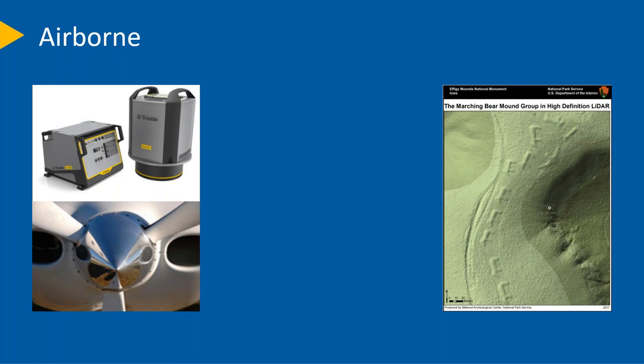Benefits you'll see from airborne LiDAR is you can capture a large area very quickly, with strong lasers and multiple pulses. So it's good for shooting through the vegetation to get the true contours of the ground. I read about these in the news quite a bit, that they'll find new civilizations using airborne LiDAR because it's able to scan through the vegetation fairly effectively and pick up these nuances on the ground to identify where buildings are. So benefits: cover large areas, can provide you a clear view of the terrain.